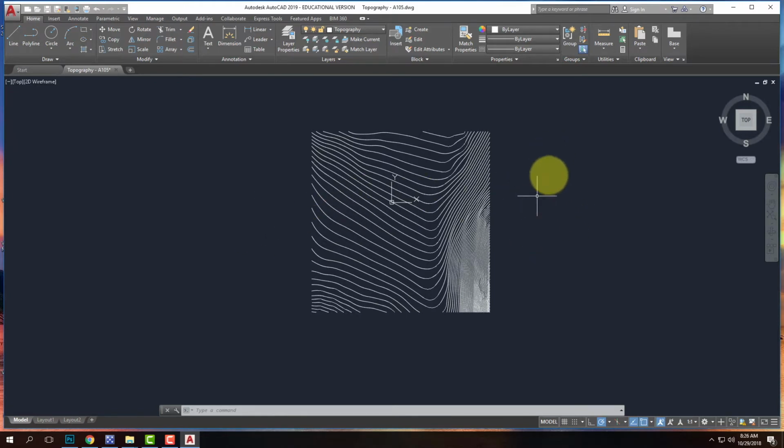The sun is going to rise over here and come around and set over here. The arc is going to go toward the south. Our best light is going to come in from the north, so big windows in the north are great. That also happens to be the direction that has the really nice view, so we can take advantage of that as well.